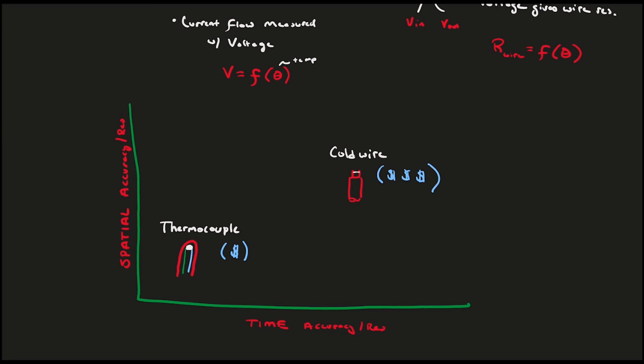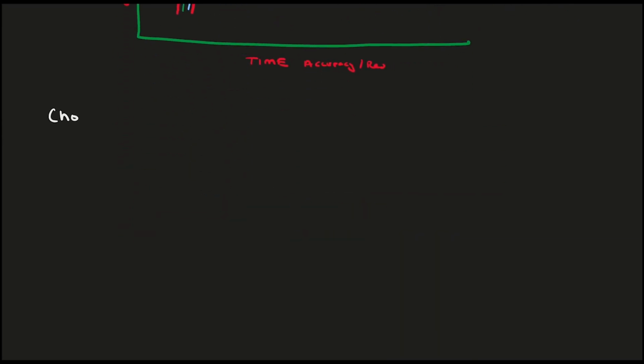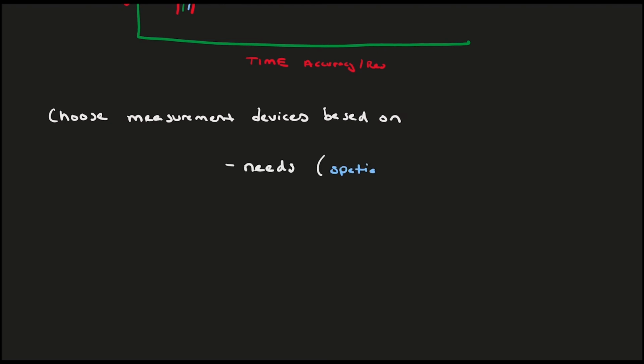To summarize, when you choose a measurement device, you want to consider your own needs in terms of accuracy and resolution in space and time. This requires having some speculation about the type of flow field you are measuring. Is it laminar and clean with large, coherent structure? Or is it a chaotic, turbulent mess with microscopic velocity fluctuations? Also, you'll certainly have some sort of budget. A PIV system is nice, but not many companies have that kind of capital for a single piece of measurement equipment.